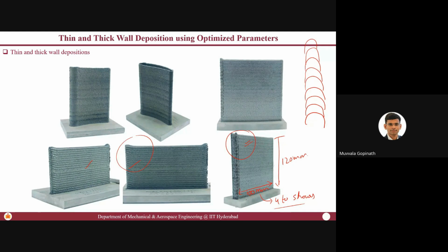Now, how do we verify? For us, when we talk about mechanical behavior, it's not just the stress strain curves. We look at the strain distribution. When you take a tensile specimen and do the stress strain curve, you get yield strength and other properties based on that. But during the tensile test, have you ever thought of measuring what the strain is over here, over here, over here?